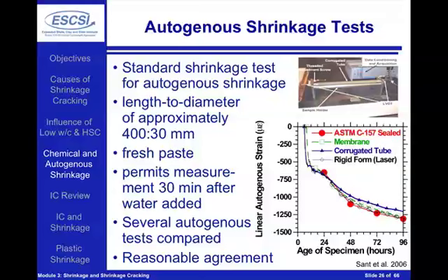And if you compare these tests and account for any of the differences or inconsistencies that may happen with leaking or temperature changes or things like that, what you'll notice is all four of these approaches can give us a very, very similar value. The benefit of the autogenous corrugated tube test is it happens to be a relatively simple and straightforward test to perform. This test has also been standardized by ASTM and provides good agreement with the other test methods that are out there.